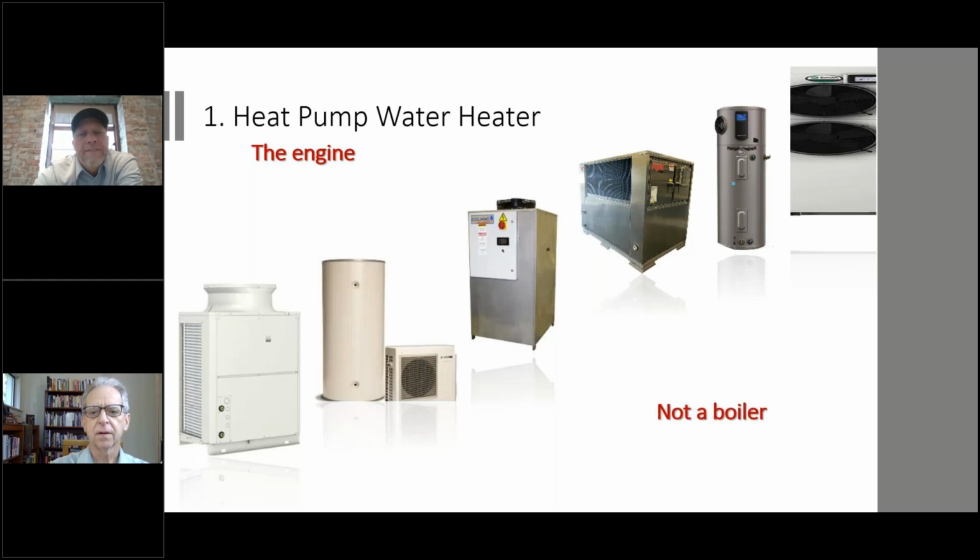This one is just making the argument that the heat pump water heater is really the engine, or the device replacing the boiler. Boilers are typically much larger than heat pump water heaters. These systems work with heat pumps taking care of a larger storage volume. So it's sort of the little engine that could, and that's how we have to think about these in our big buildings and small ones.